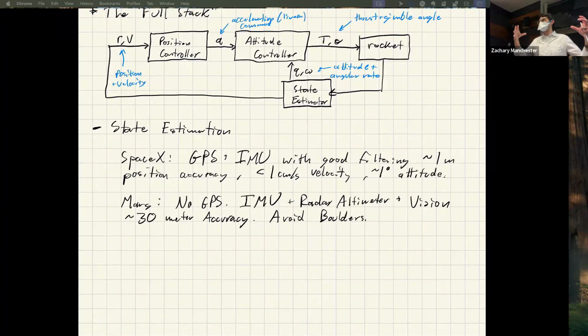Space Network, which is a series of dishes on the Earth. There are various techniques. The state-of-the-art stuff is called delta-DOR. It's basically measuring the difference in time of arrival of signals at two different dishes on opposite sides of the Earth. Essentially you get some angle information from that. You also get a range measurement and a range rate measurement, the velocity component along the range direction from Doppler, and some angular information from the delta comparison, but that's quite bad.